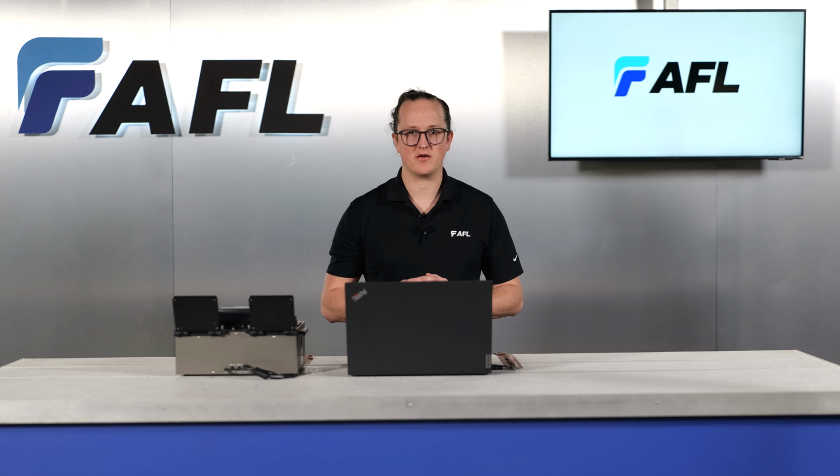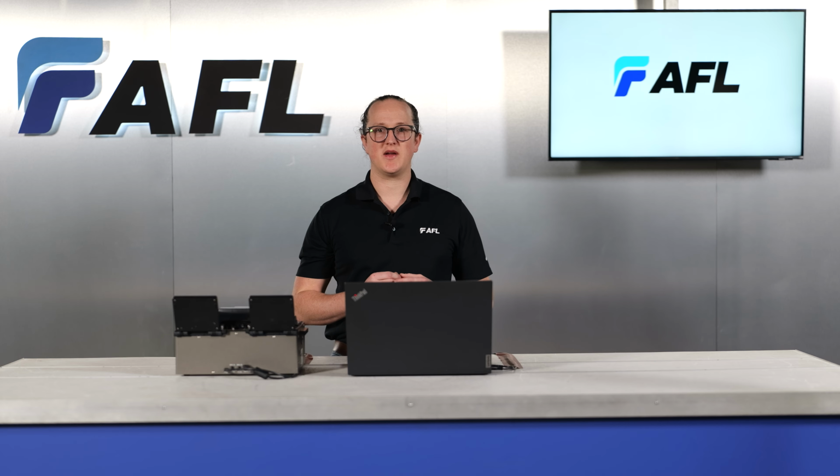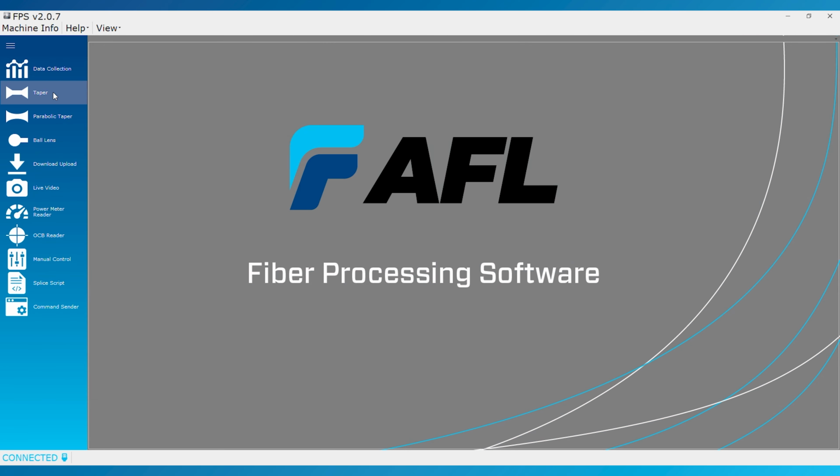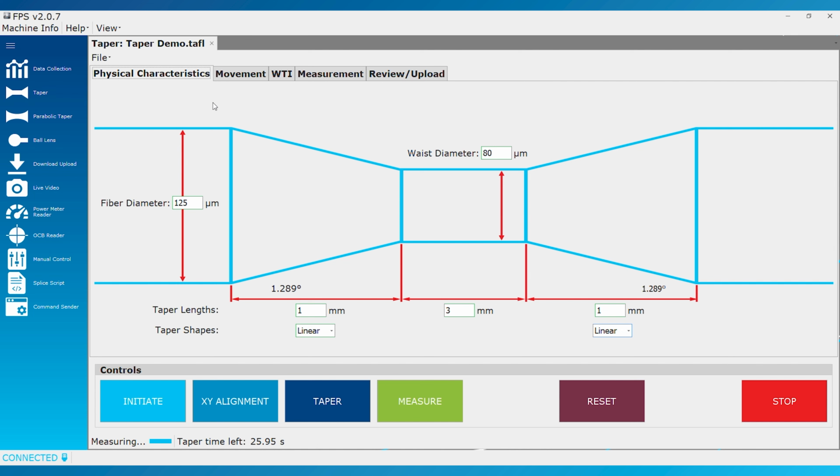The next module under fiber shaping is the taper module. This function allows us to create tapered fibers by systematically adjusting fiber diameter, taper lengths, waist length, and taper shapes. The taper module landing page is where you define the fundamental design parameters for the taper you want to create. To begin, input the following: the fiber diameter, the tapered waist diameter, taper lengths, waist length, and taper shape.